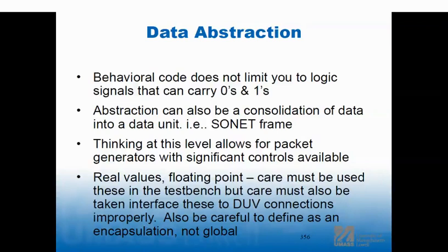But if it's the more functional interface, the thick interface that I'm talking about, then what it's going to do is actually receive the message, decide if it has a proper destination address, a proper source address, right? You get the idea. All of the stuff, it's going to check the CRC, and then it's going to produce a result to the test case that says, I just got a message. This is when I got it. The payload was random, or maybe you do a check on the payload. The CRC passed. This was the source address, and this was the destination address, just as an example. So now the test case just monitors this bus function model for good and bad packets.